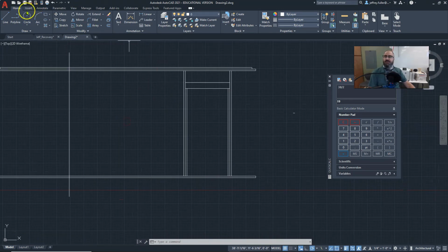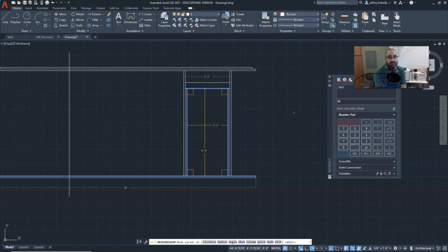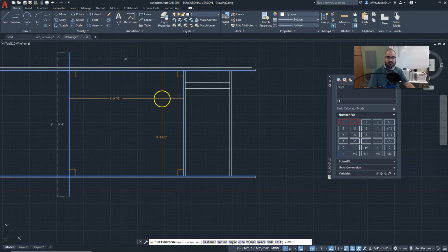All right, so if we end up here, we should end up with a little bit bigger than 36 inches. So I got 3 foot 2 inches. That leaves me that 2 inches of wiggle room when I put the door frame in there from the building supply store, and I'm able to get some wiggle room and some expansion space and all that.